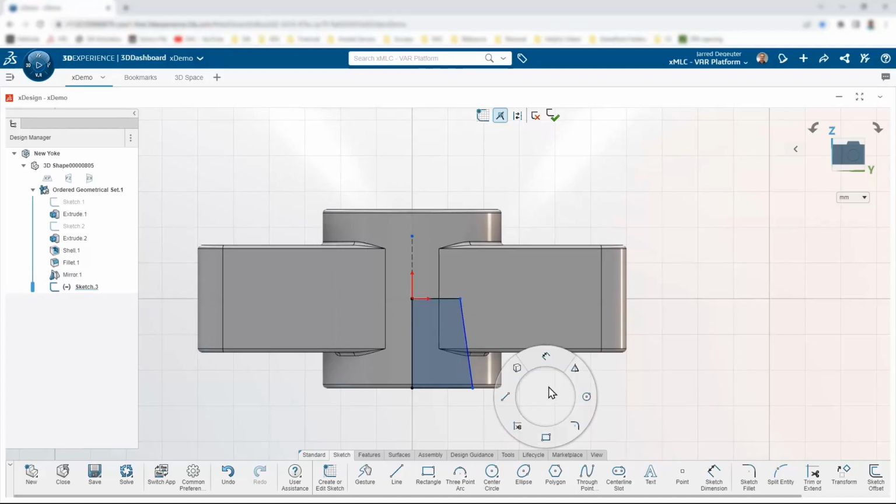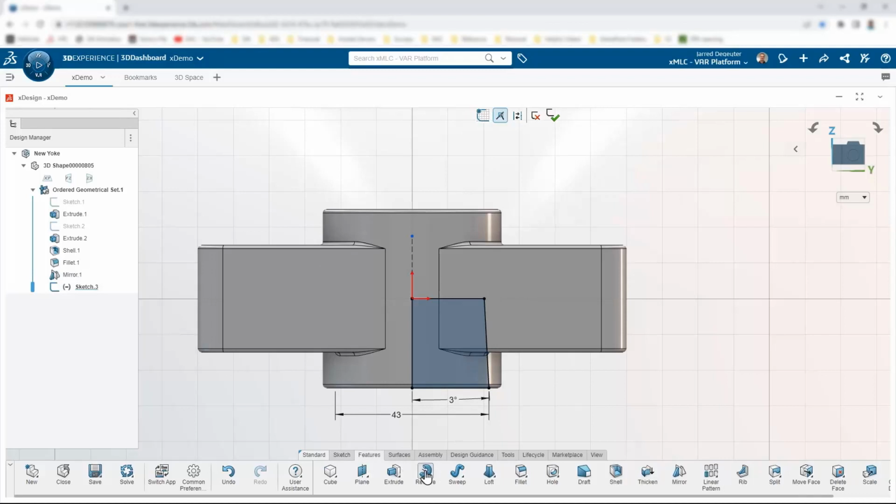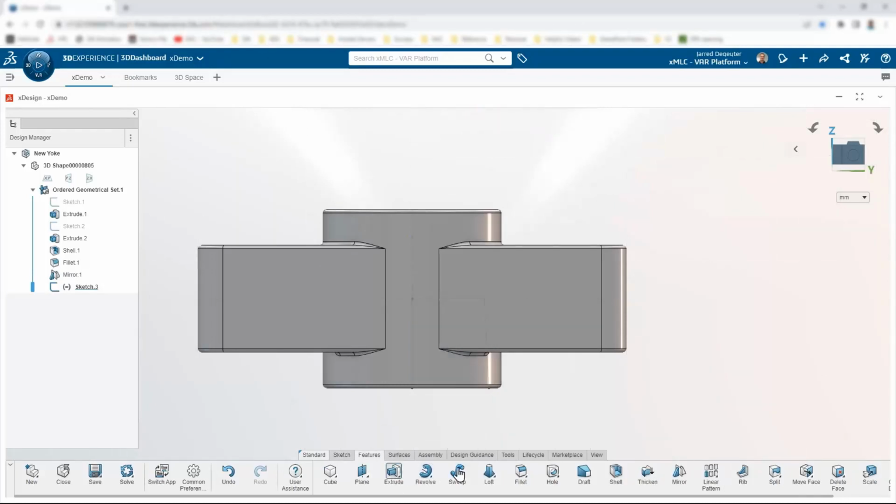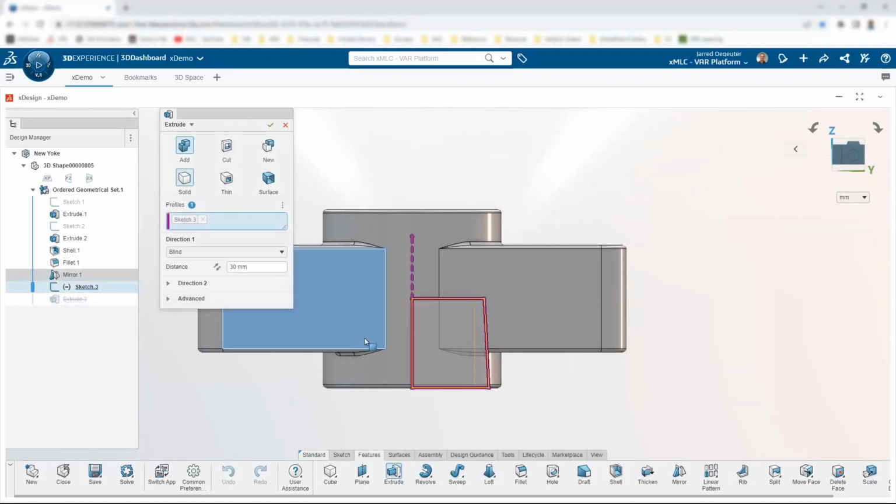By the way, you might be happy to know that the diameter style dimensioning technique that you have from SOLIDWORKS is carried over here as well. So we can come in and drop in that easy to use diameter dimension. Pop in our angle. And we should be ready to do our revolve. Okay, cool. So, I just went in and I accidentally clicked the extrude button instead of the revolve.